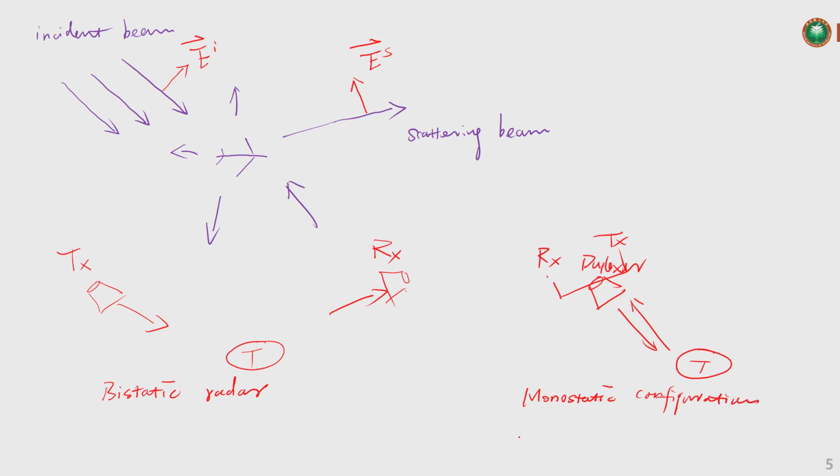The monostatic, we can also call it backscatter, right? So the first one is bistatic scattering, where the scattering components go forward. And the other one is for the actual radar system, which uses the backscattering to get the backscattering components. So both components of both configurations should be treated separately for their expressions.